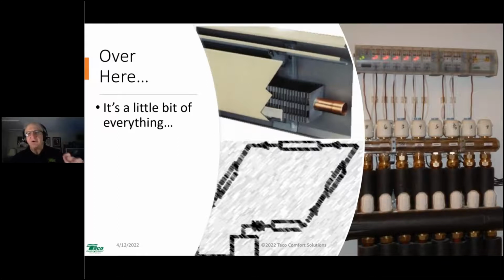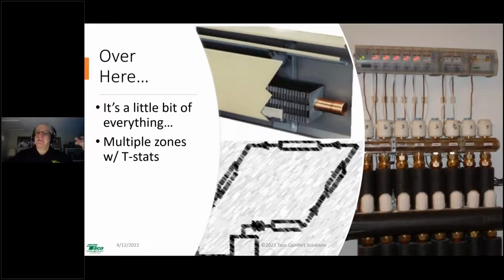And these systems were installed in houses while the houses were being built. So we had big pipe designed to a 20-degree delta T, big pipe, big loads. We're going to have higher flow rates, but because we're using larger pipe, that head loss is going to be lower. And because we zone with things like zone valves, that high flow, low head, flat curve circulator works with zone valves in particular, but even with zone pumping, beautifully.